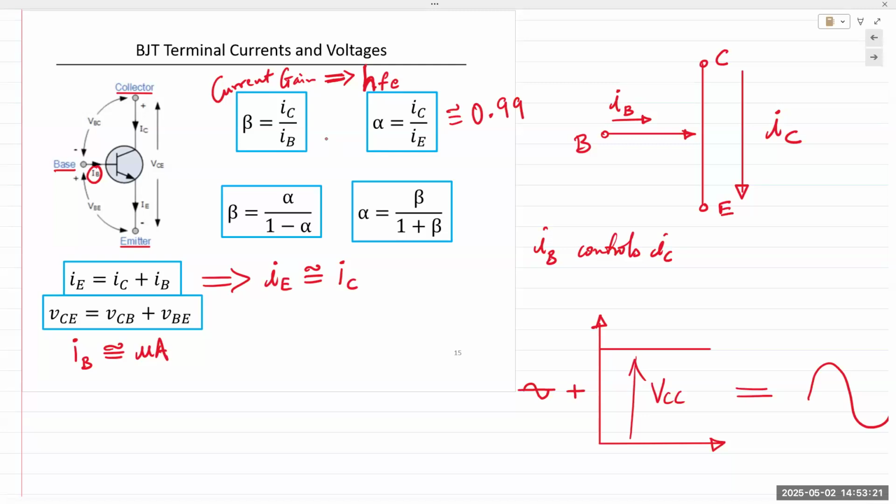The 2222 transistor has a beta ranging from 35 all the way to like 200 or 300. Very large range. We say that's the typical range. That's what the manufacturer tells us. And the reason, of course, is simply that when we manufacture or fabricate these devices, we can control the amount of atoms going in, but we cannot control it beyond a certain point. We cannot control it down to a single atom. It's impossible. Not even to thousands of atoms, right?